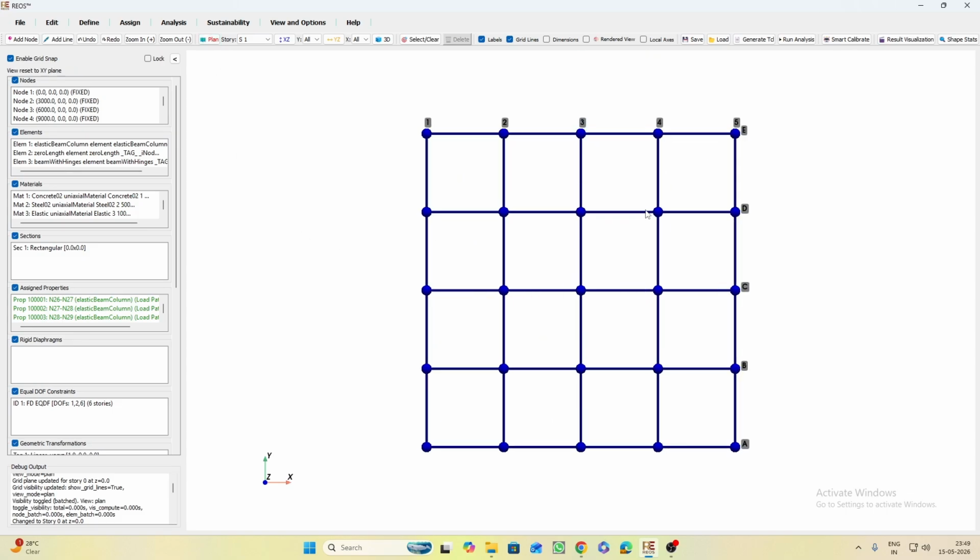In this case, for the infill frame loads, we will not consider the roof level members because there will not be any partition wall on the roof level, although there will be a parapet wall. But for this example, we are not going to consider the parapet wall load. So we are selecting the members again.